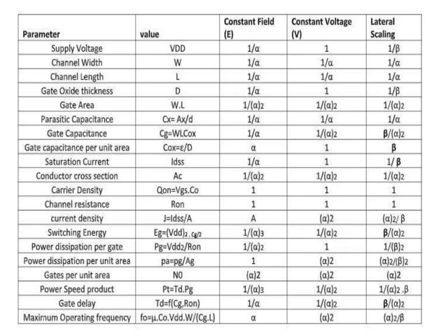Why? For constant field scaling, we have already mentioned that alpha equals beta, whereas for constant voltage scaling, the value of beta is 1, so only the factor of alpha remains. In constant field scaling, alpha and beta are equal, so you can always put alpha in place of beta.